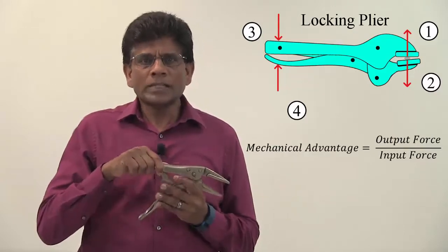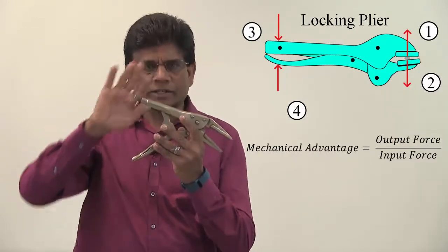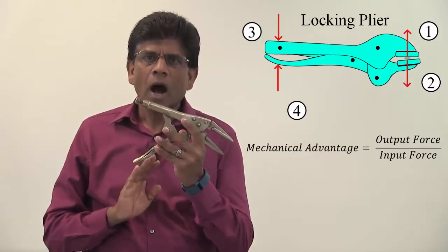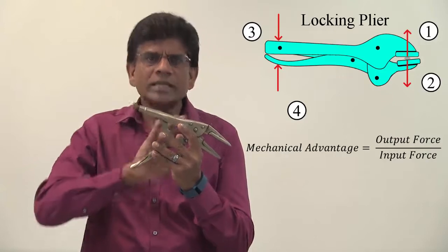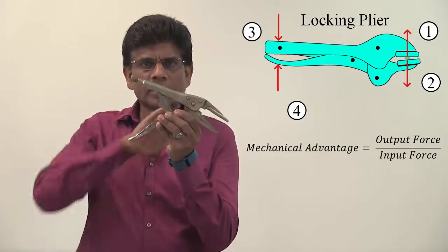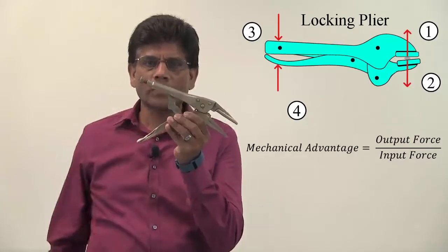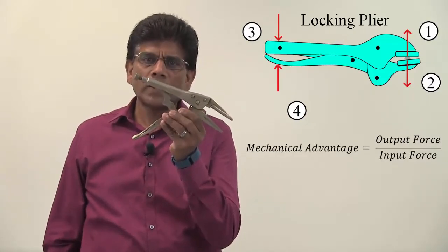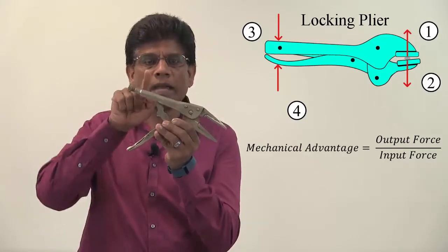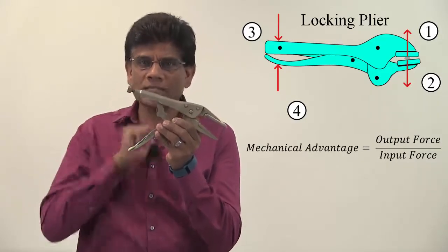First, we'll see if we can draw the free body diagram of the entire structure so we can calculate the support reactions. Often in case of machines, this is not possible. For example, take a look at our plier. There is really no support reaction from the ground. So in problems involving machines, we have to draw the free body diagram of individual members and then solve.